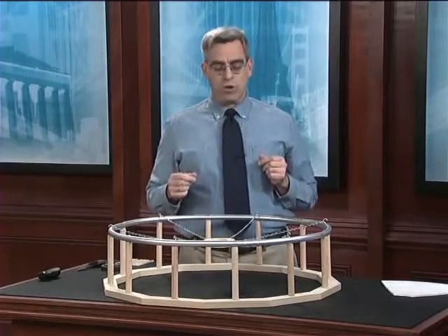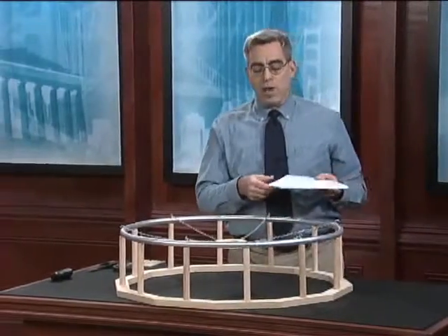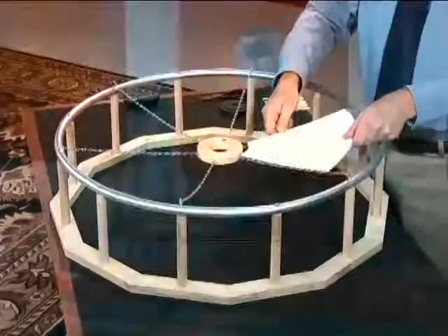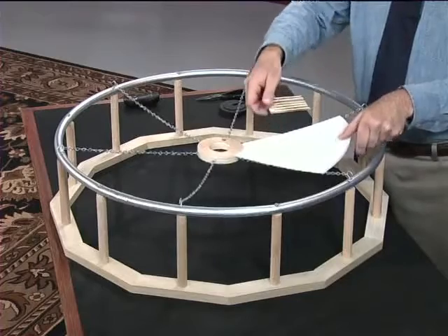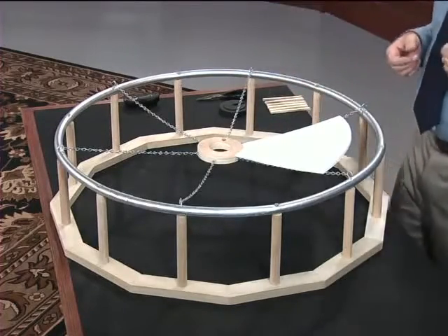But this is how the system works. Of course, we need a roof over the building, and the roof was created by simply using precast concrete panels, which were then put in place on top of the cables and used to support the roof loads that were applied to the top of the building.